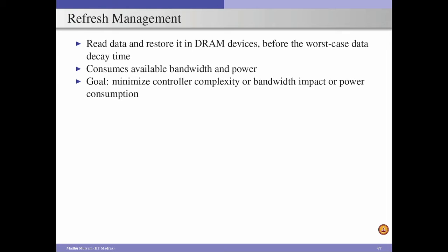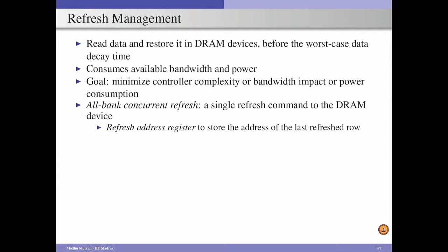There are several refresh management techniques proposed in the literature, but we are going to discuss basic refresh management techniques in this module. In order to reduce the complexity associated with the DRAM memory controller design, one simple technique we can do is, we will go for the all bank concurrent refresh mechanism.